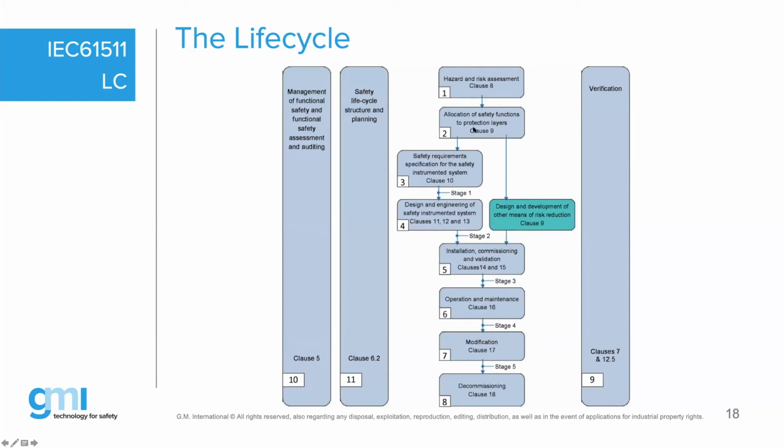Based on this, we're going to do, in the second phase, we're going to do LOPA. LOPA is nothing more than layers of protection analysis. And layers is layers on top of each other to try to protect your unit. So that LOPA is in some cases, in some, let's say, end user applications, not allowed to be used. And I personally like this.